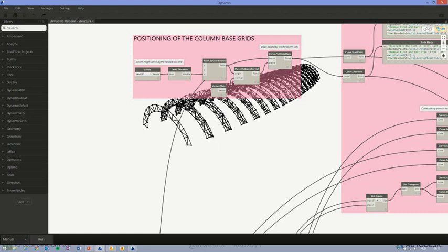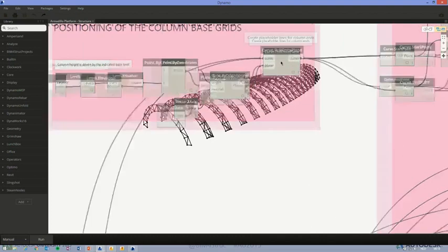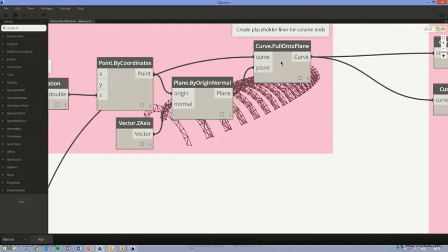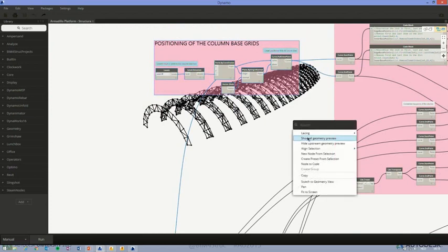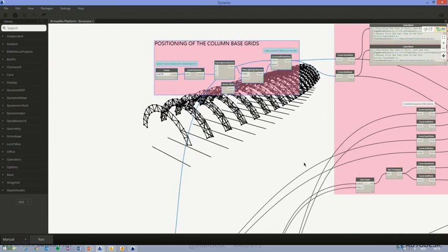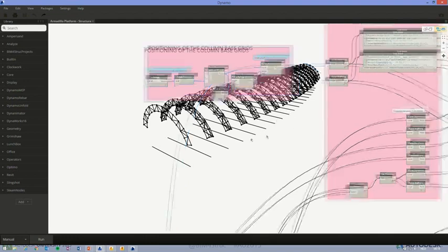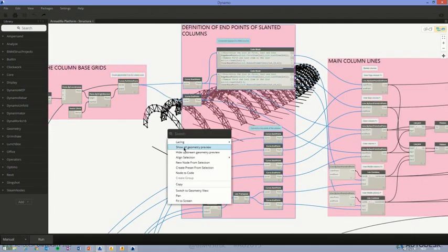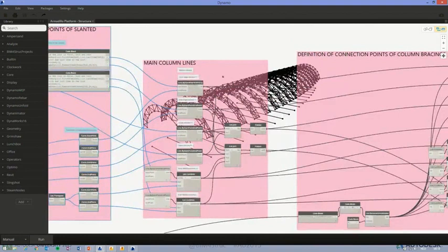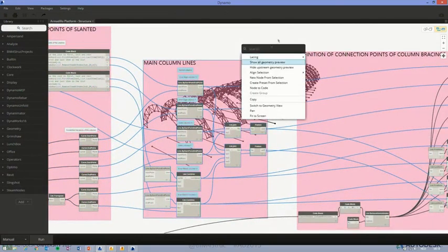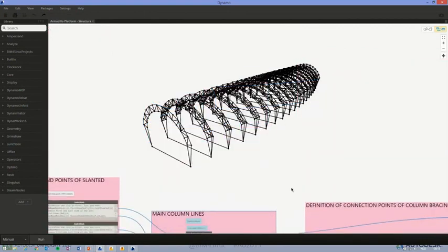Now, for the bottom chords, we also need those specific curves. Therefore, we can use an offset. That offset will generate a curve that, in any position, you would draw a line which is perpendicular to that curve. It will represent the height of that truss. In this case, I want to have a truss height of 1600 millimeter. Okay? So this is what curve offset is doing. If I select this node, you can see them in here. Let's switch off this face, because it's too dark otherwise. And then you get this. Now these are the bottom center lines. I want to have a spatial truss, so you have to copy those lines again to the outside of these lines.